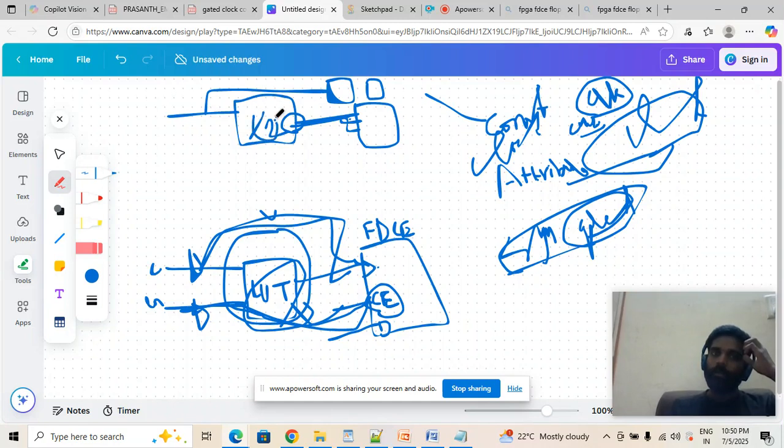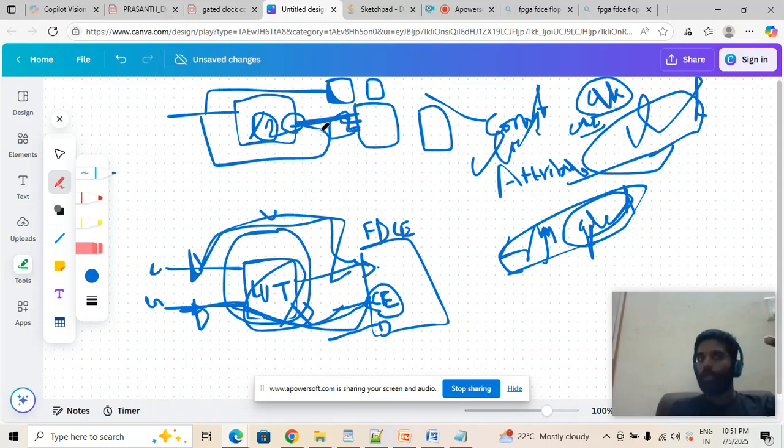This derived clock path, we are applying the clock gating. When you apply the clock gating, it will shift to the clock enable port, right? So during that time, the constraints we are writing might go wrong, so the tool will give you some different inference, and maybe it may try to use the same clock to this place, and this will go into the clock enable port. In that case, the circuit may not operate at the clock frequency we wanted. We are expecting it to operate at half of the frequency, but unfortunately, when you apply the clock gating, the tool assumes it's a gating logic because we are just doing the divide by two, right?